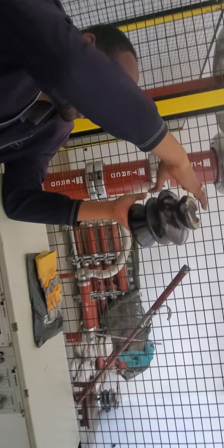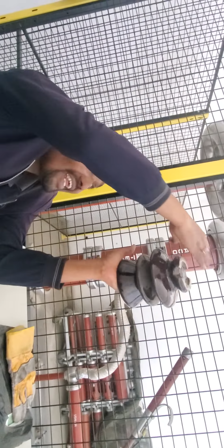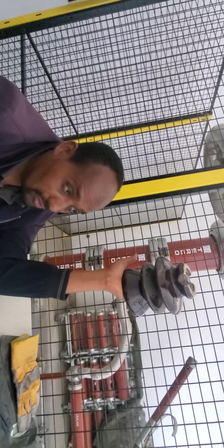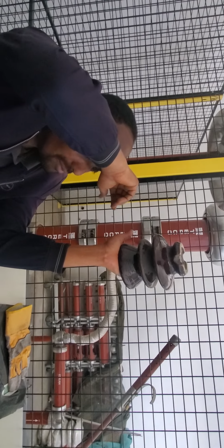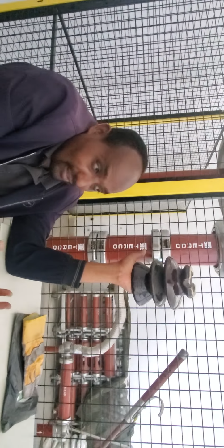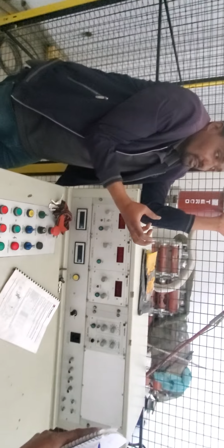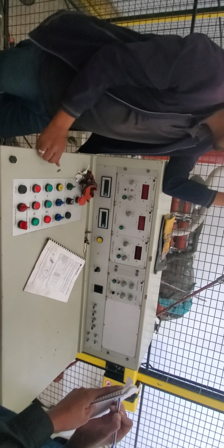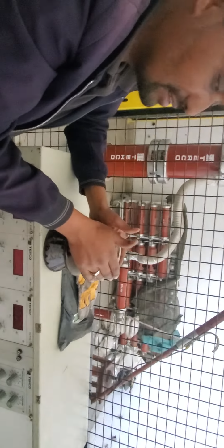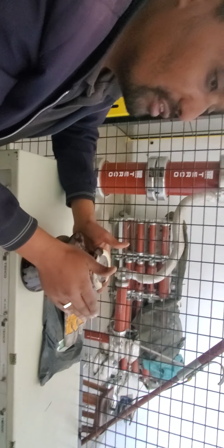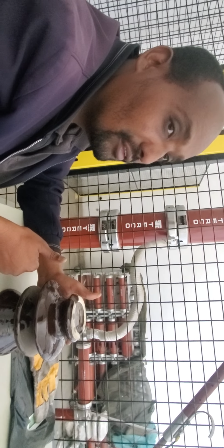Flashover voltage will, here we have what, the air around. So under dry condition, the air around this insulator will break down at 70 kilovolts. Under wet condition, it will break down at 55 kilovolts. Why? Because under dry condition, the air is what? More insulating. Under moisture condition, the air is what? More conductive. So now under dry condition, we are connecting this insulator. Then we are going to supply 70 kilovolts. If there is flashover around this at 55 kilovolts, but the standard is what?